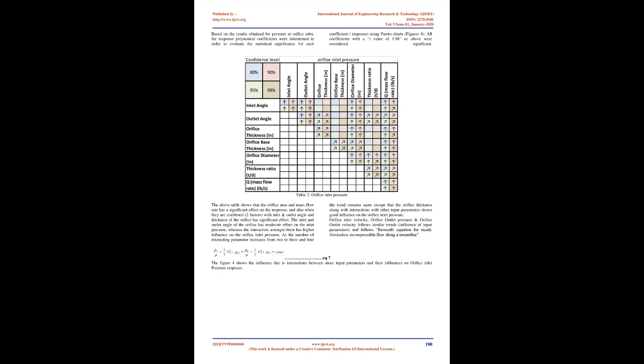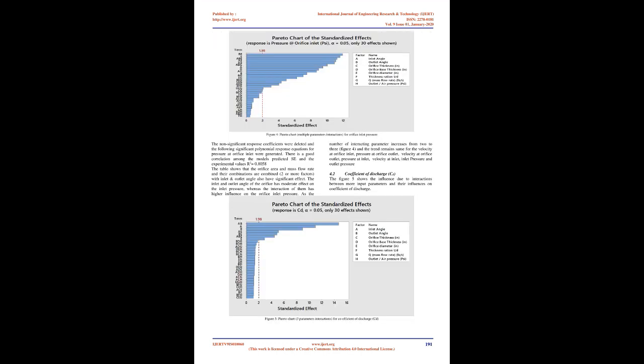The mass flow rate, which is directly related to the velocity of the flow, is one of the key parameters to evaluate the effect on different response parameters. Even the absolute total pressure varies from inlet to outlet. It can be seen that the maximum value of the absolute total pressure starts decreasing once the flow crosses through the orifice. The major effect of any parameter, from the minimum value to the maximum value, can be observed only near the orifice. That means the orifice area is very critical to the various response parameters.